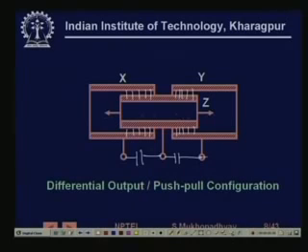And as this is moving here, if it moves to left, then the area is increasing, so this capacitance is increasing, and by an equal amount this capacitance is decreasing, because the area increase of this is exactly equal to the area decrease of this. So you can say that if it is C plus delta C, then this is going to be C minus delta C.